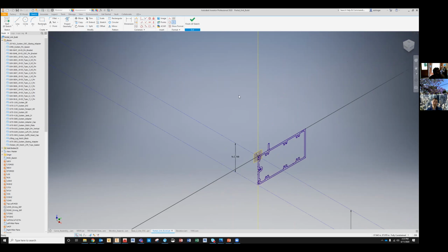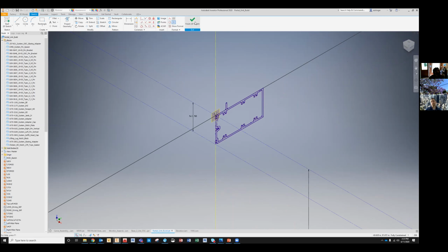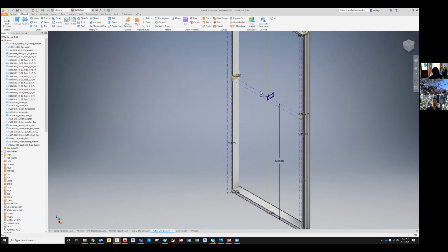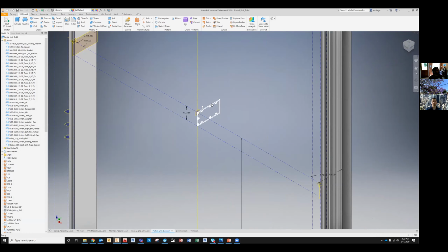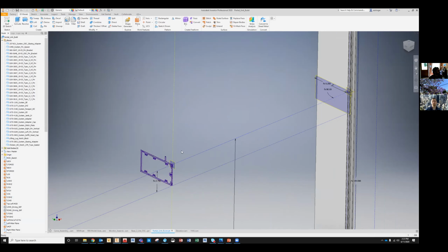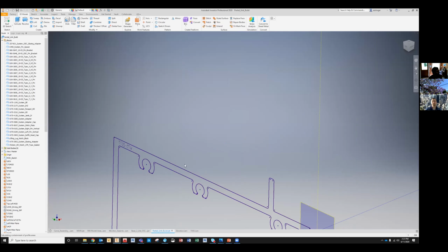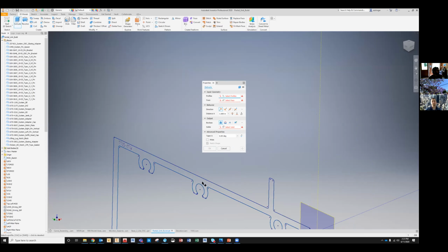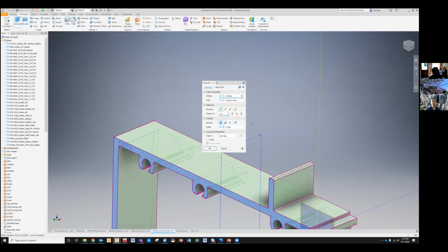After that's been placed, you click finish sketch, and we're going to extrude this sketch to this plane here and this plane over on the right hand side. So the palette comes up and you click on the profile and select new solid. If you don't select a new solid, then it basically blends this part in with it.